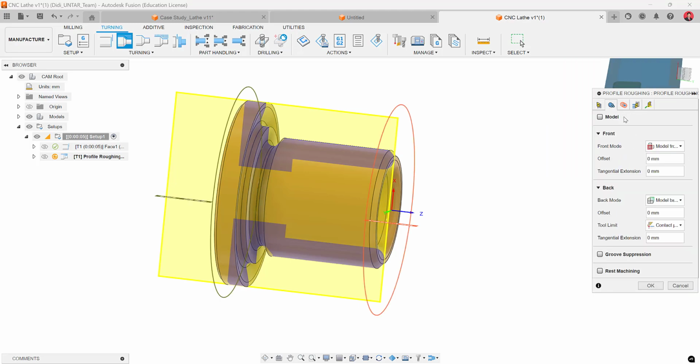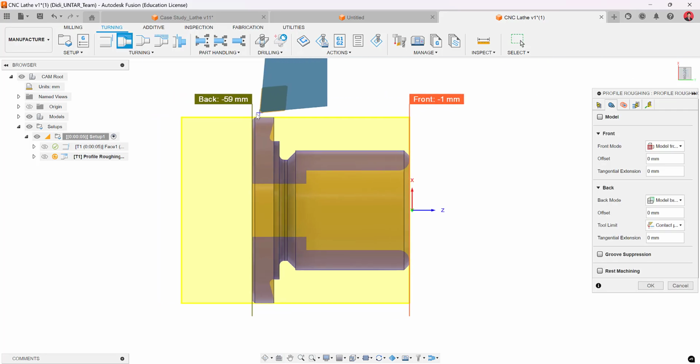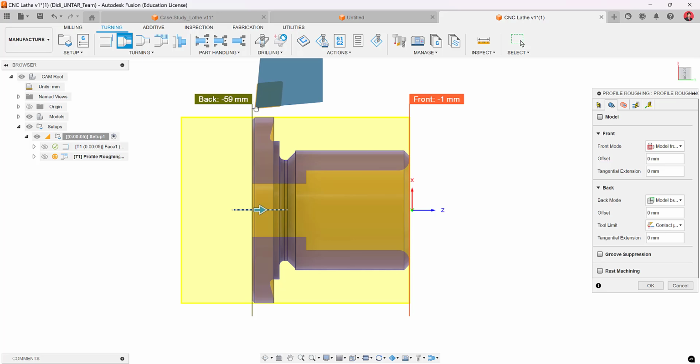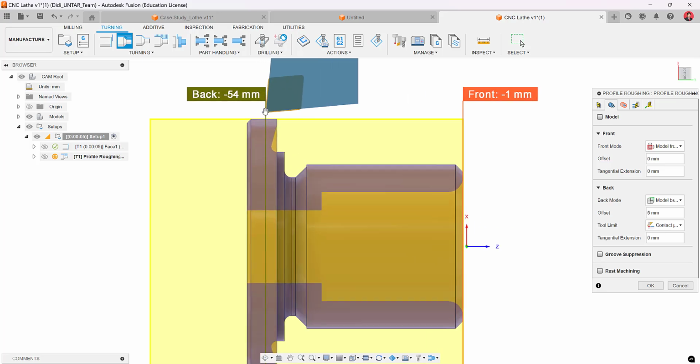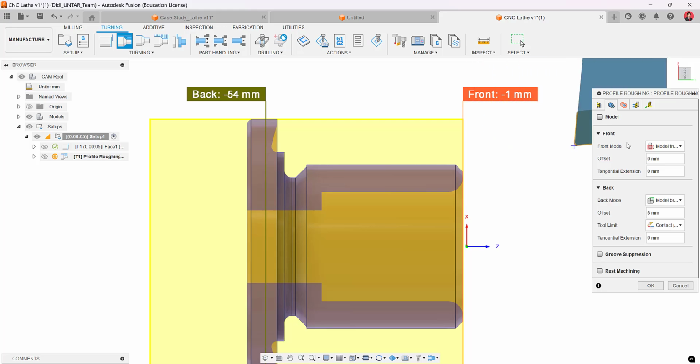And then this is for the containment of the area which is going to be roughing. So I just want to create a roughing in this particular area, and then I will slide back a little bit for this containment area, and then the front one will be 0.1, okay. And then the offset is the same parameter to offset that one.